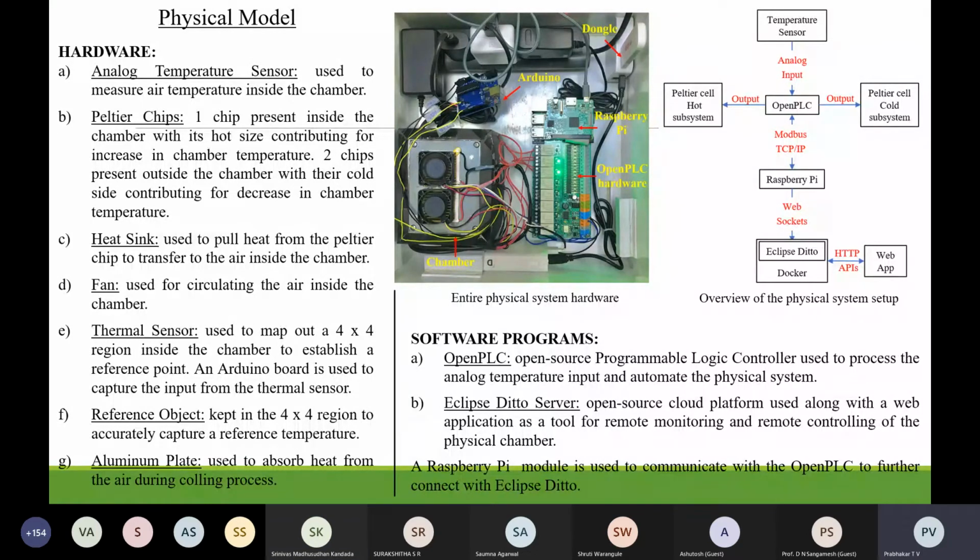So one approach is through Matlab, which you mentioned, and that has to be done in a particular way. That is, you convert it into C code and download it as an executable onto your controller, microcontroller. The other is to run a PLC code like what I showed you. Okay, sir. Thank you.